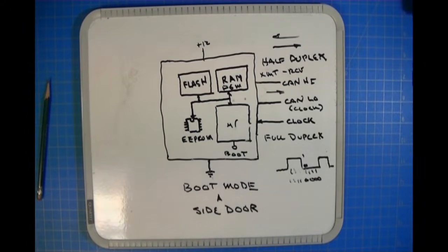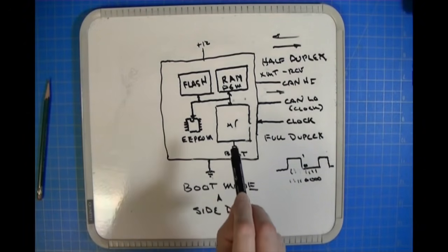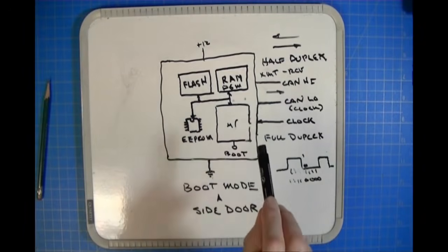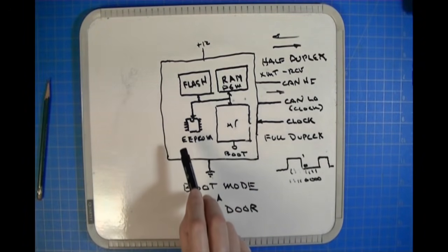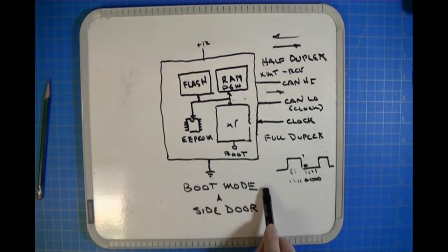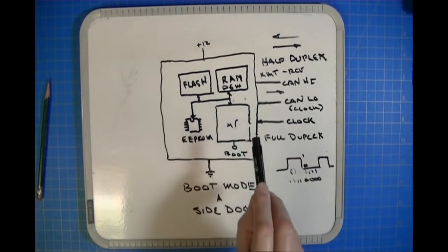That's what boot mode is. And boot mode, I decided to call it a side door because a back door is what BDM is. Okay, BDM is directly accessing the flash memory, the RAM, I/O, EEPROM through a hardware interface. Okay, boot mode does it through a software interface.